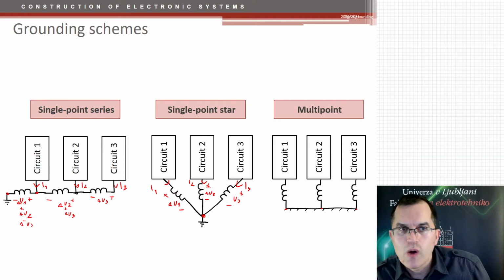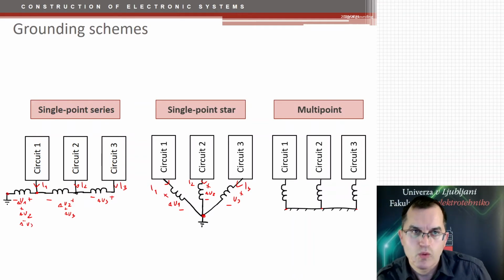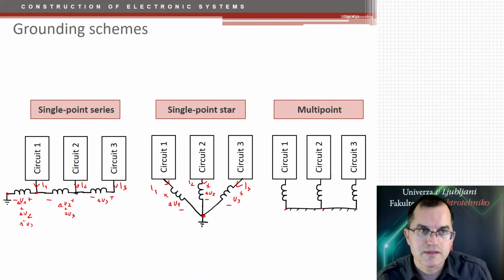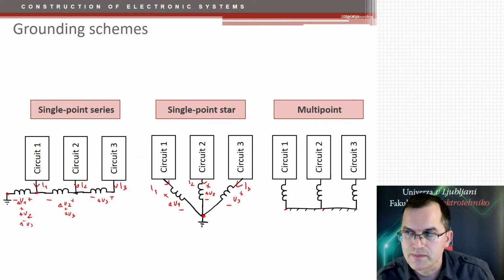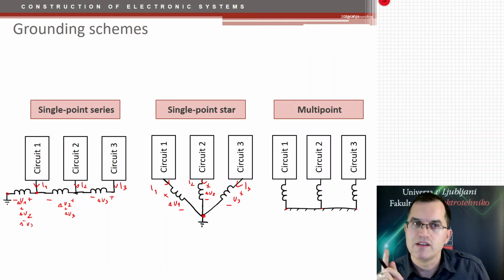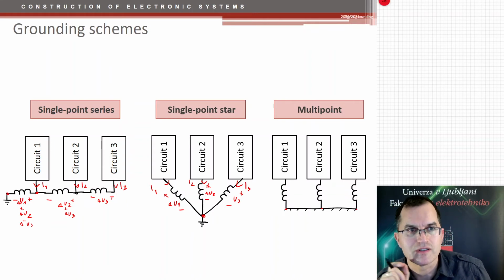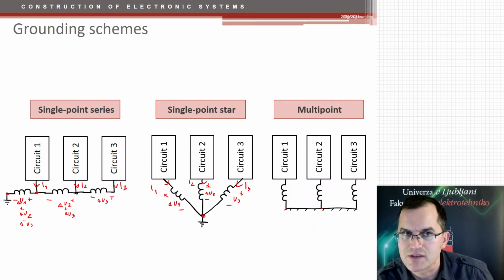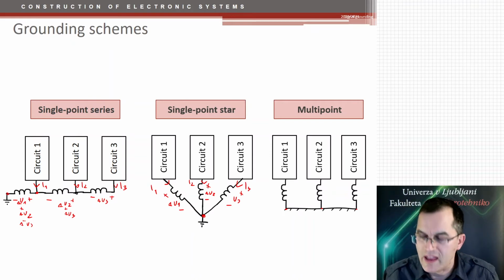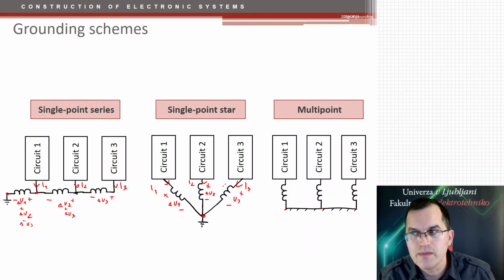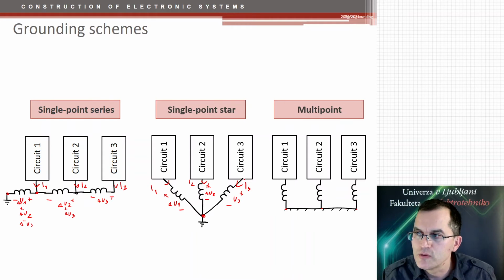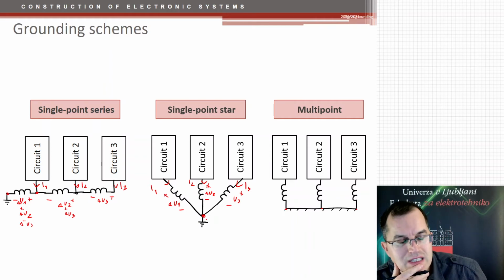So the question is, why wouldn't we connect all of that like that? Why wouldn't we connect every circuit in our PCB like that? Well, the answer is because we can't, and it wouldn't be practical. And the other thing is, please do not forget about the return currents on ground for high-speed digital circuits. These return currents would then have to flow along high impedance traces, because that couldn't be done by a ground plane. You have to have traces to connect each ground separately to a single ground point.